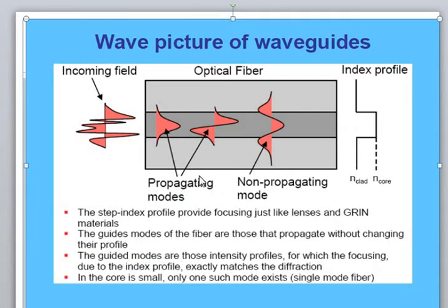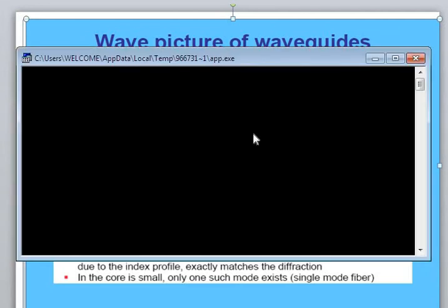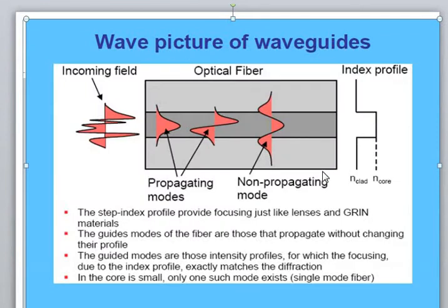The modes that appear here are the bounded modes, refracted modes and the leaky modes. The order of the mode is equal to the number of field zeros across the guide, the crossing pattern. So here m is equal to 1, m is equal to 2 and m is equal to 3. The order of the mode is also related to the ray congruence corresponding to this mode.